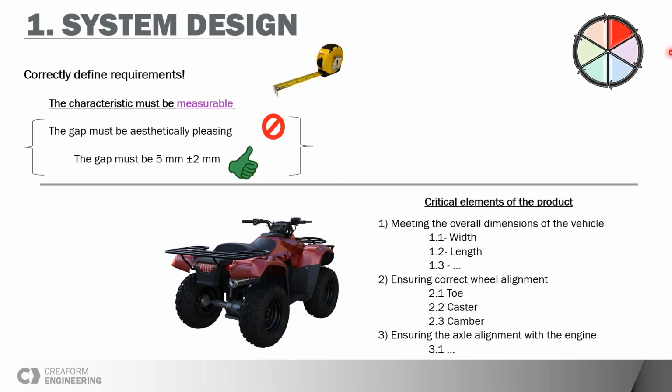Yeah. Of course, if we take the whole cycle, if you make a train, it takes time to develop the train. So right from the beginning of the design phase, you're going to have dimensional management in mind. So if you do the whole cycle, and it takes 2 years, 3 years to get the product to be first manufactured, well, you can imagine that the cycle time is long, since now you're going to start manufacturing the product. So suppliers send you the parts, and you assemble them within your factory. Then you find out you have certain issues, so then you have to inspect, make sure it's all okay, go back to the engineering. So a full cycle in this case might be years.